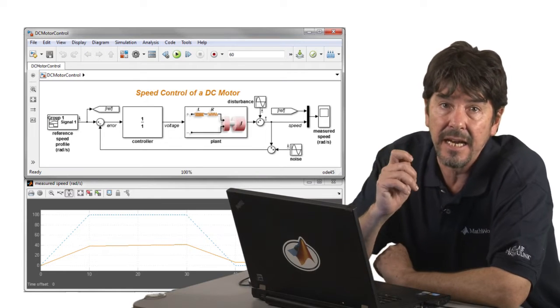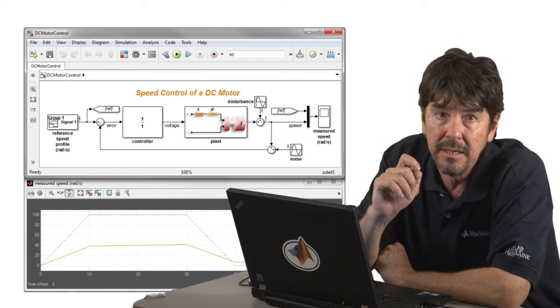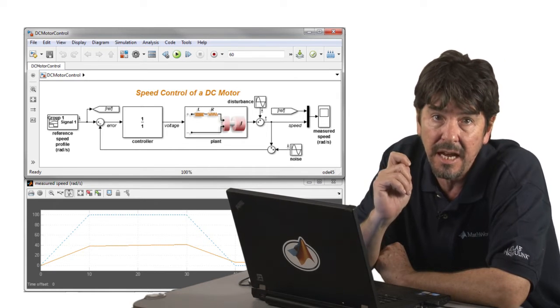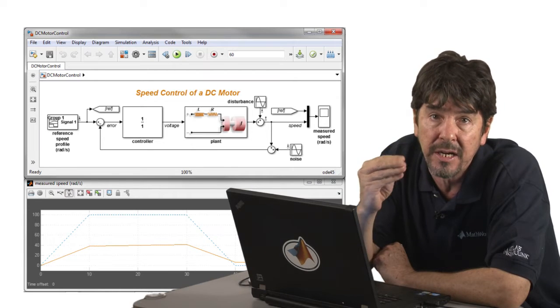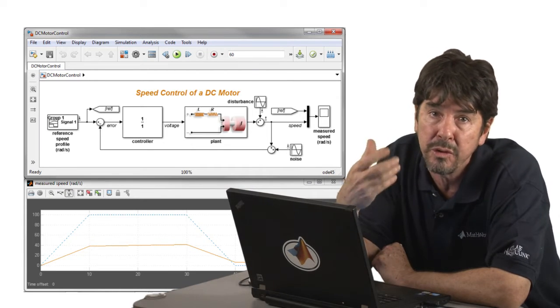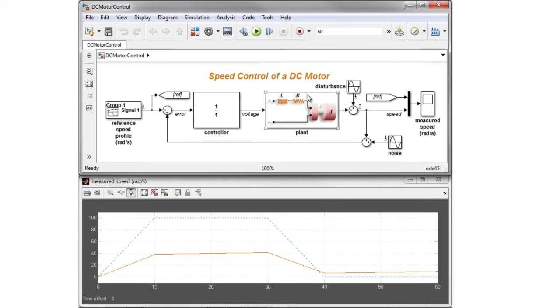Just as an aside, I know this is a relatively simple example, but as control design engineers, I hope you can appreciate the beauty of a tool like Simulink. Not only can I graphically build any block diagram or closed-loop architecture I can imagine, all I need to do is press the play button and boom, I can observe the transient response of any signal in my system. In addition, I can mark my input and output points of interest directly on the diagram and let the tool extract the transfer functions that correspond to all the loops I just defined.